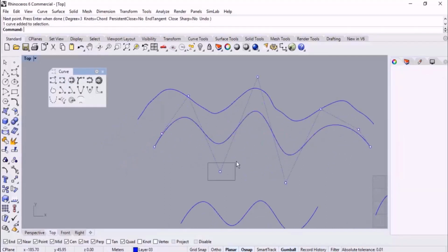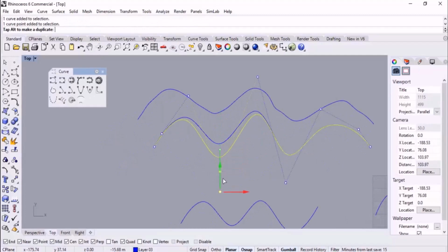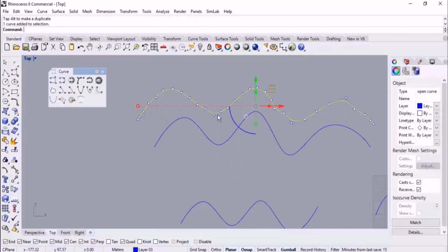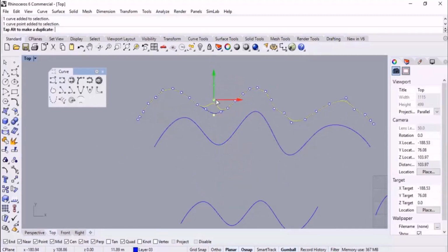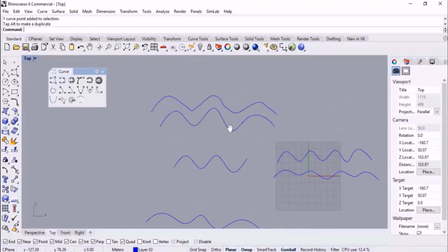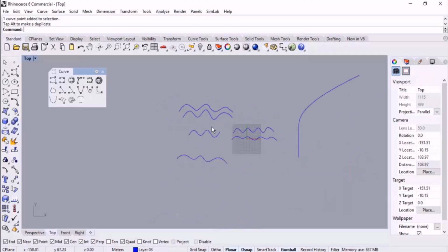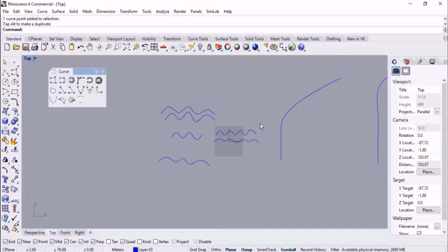Check this out. This is not satisfying or acceptable, and we won't be able to modify the curvedness of the line. It would be very difficult since we got too many control points. Check this out. It wouldn't be practical. So while you're sketching your curve, note that. Try to have fewer control points, so the fewer the better. Let me say, at the count which is required or you need.